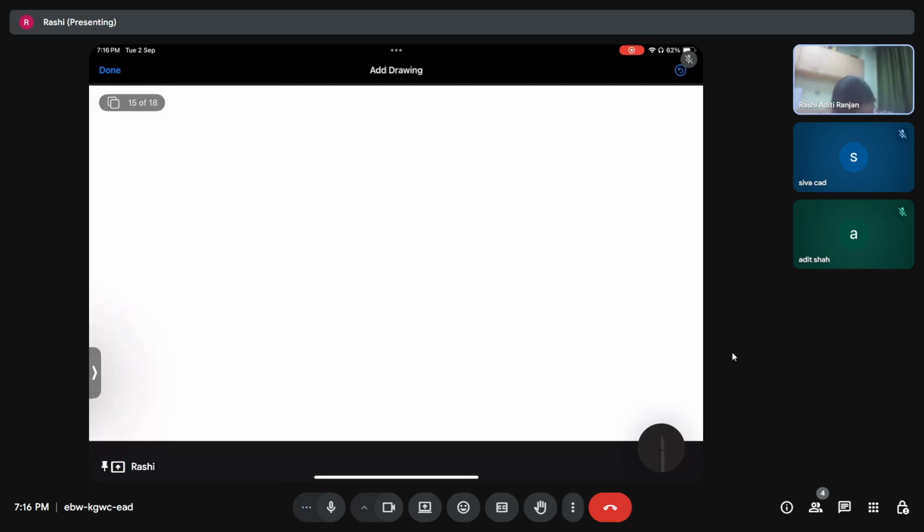We are going to get mx double dot plus cx dot plus kx is equal to k into y of t, which is going to give us kr 1 minus cos of omega t plus kL by 4 r square by L square 1 minus cos of twice of omega t, right?